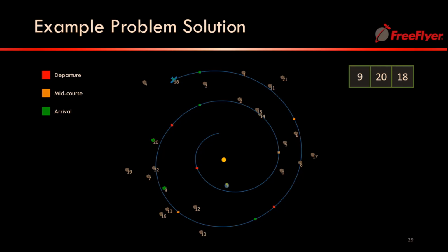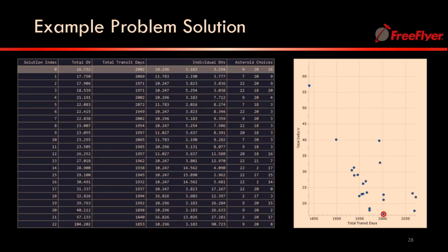But you as the engineer are able to look at the data that the multi-objective optimizer comes up with and make a decision based on all of the trade-offs that are available to you. Whereas in a single objective optimizer, obviously you're only looking at one objective, and you can use that single objective in creative ways and come up with interesting ways to combine all of these objectives into one value. But multi-objective optimization has the advantage of allowing you to examine the entire front of trade-offs and make a decision based on that information.